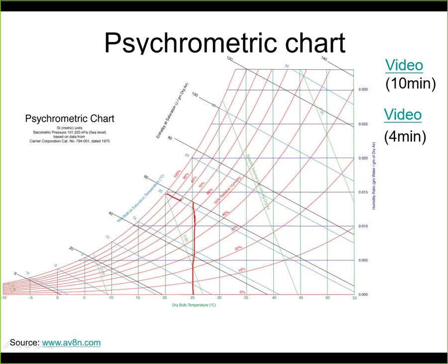here. So here we are looking for this intersection, and we see that those red curves give us relative humidity. So in my example, the relative humidity would be something like 60%. It is accurate within a few percent. So it's possible to build a very simple hygrometer like this.